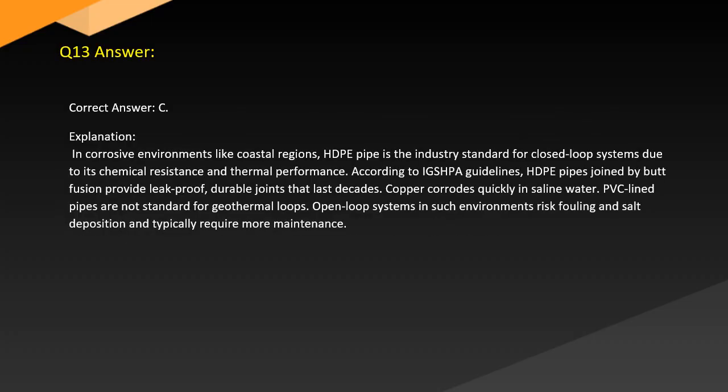Answer. Correct answer: C. Explanation. In corrosive environments like coastal regions, HDPE pipe is the industry standard for closed-loop systems due to its chemical resistance and thermal performance. According to expert guidelines, HDPE pipes joined by butt fusion provide leak-proof, durable joints that last decades.